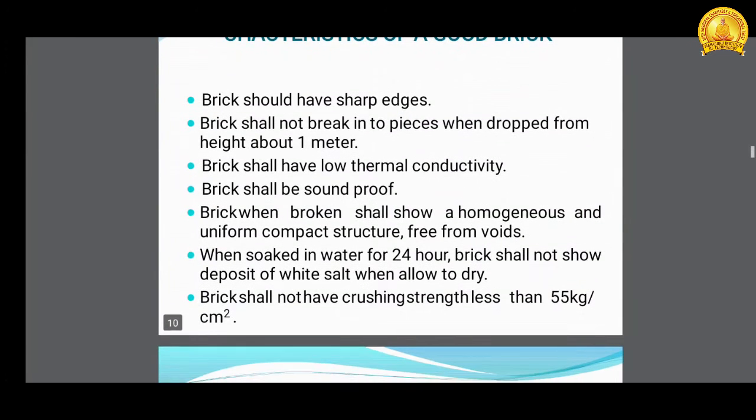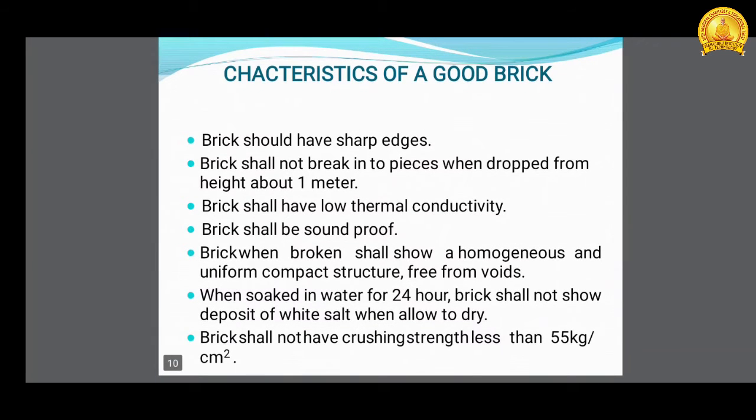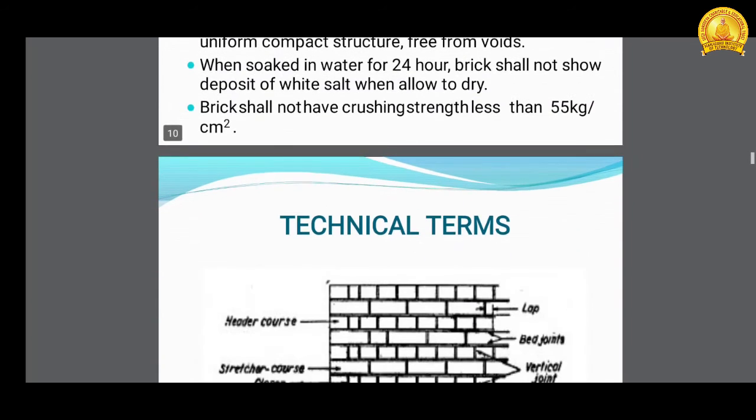Brick when broken shall show a homogeneous and uniform compact structure free from voids. When soaked in water for 24 hours, brick shall not show deposits of white salt when allowed to dry. Brick shall not have crushing strength less than 55 kg per centimeter square. These are the important characteristics of a good brick.